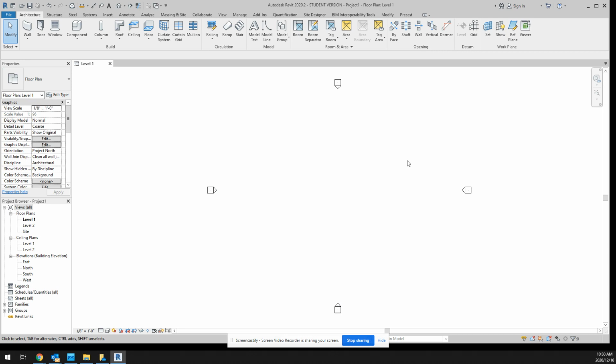So we want to make sure that when you're drawing your floor plan that you keep it within this view area. If I start drawing something out here, then when I start looking at my views and my elevations, part of your building will get cut off because it's not in the view range of the north, east, south, west markers here. So always make sure when you eventually start drawing your walls that you draw it within this area.